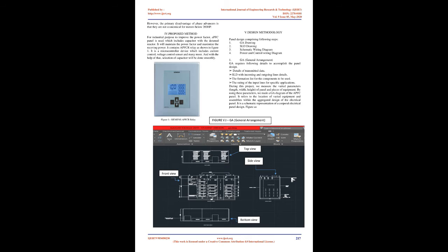2. Need for power factor correction. Varying power demand on the supply system. Power factor, cos φ, also varies as a function of the load requirements. Difficult to maintain a consistent power factor, cos φ, by use of fixed compensation. Leading power factor under light load condition. Automatic variation without manual intervention, of the compensation to suit the load requirement. Increase available power. Reducing the installation size. Reducing the voltage drops on installation.